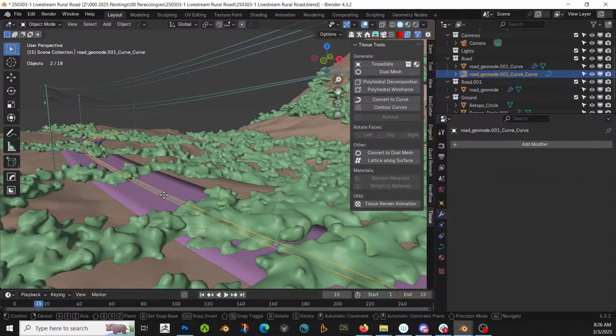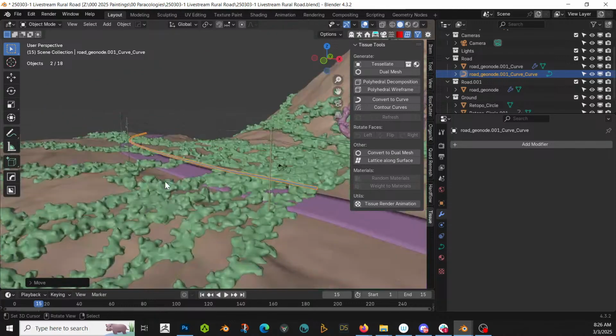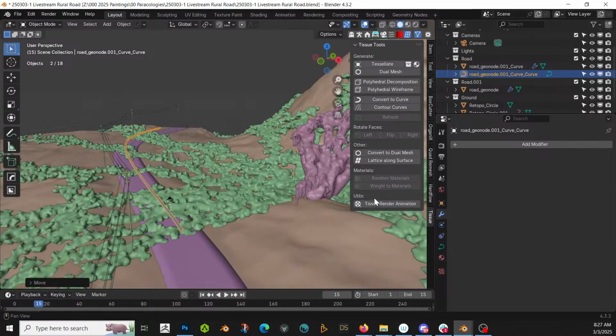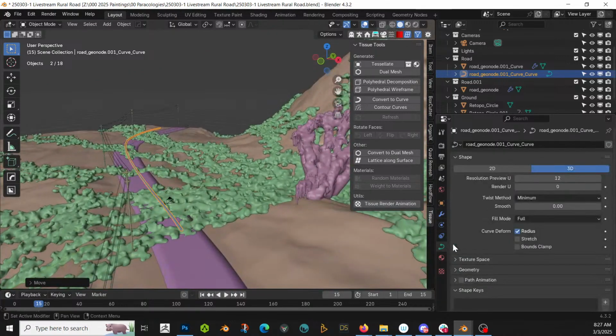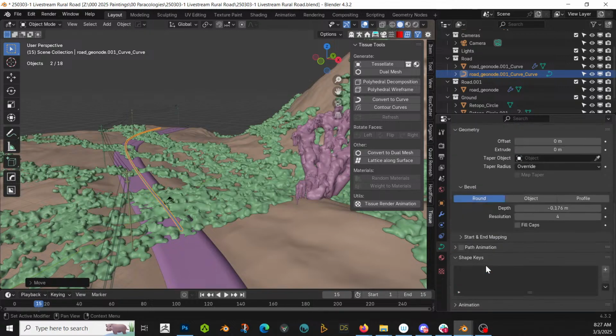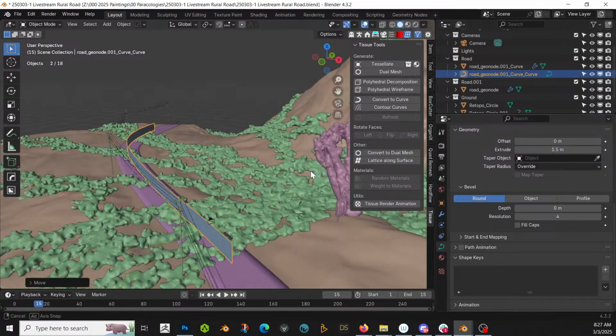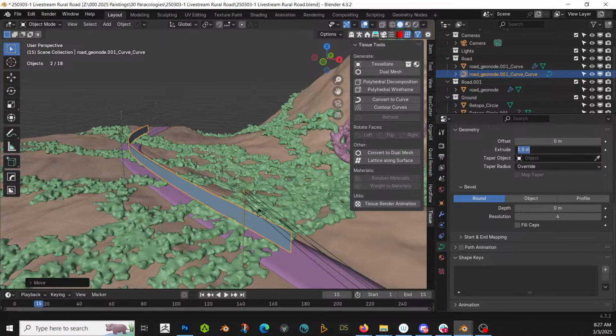This thing here, GZ, let's bring it up above it. There we go. And we're going to kill its bevel, an offset of 3. Not offset, sorry. Extrude of 3, 1.5, because it's radial. 1.75. Okay.